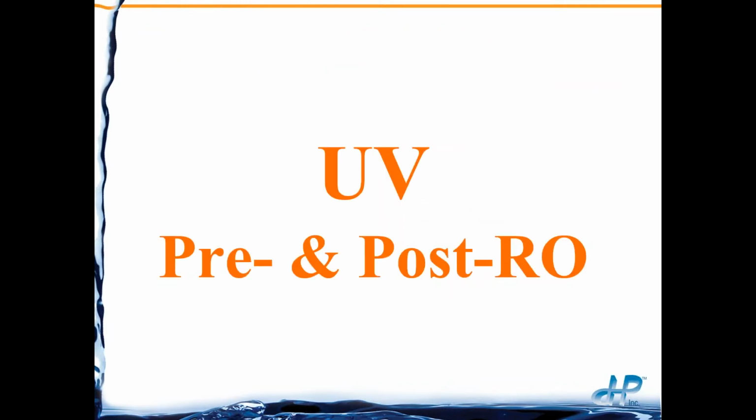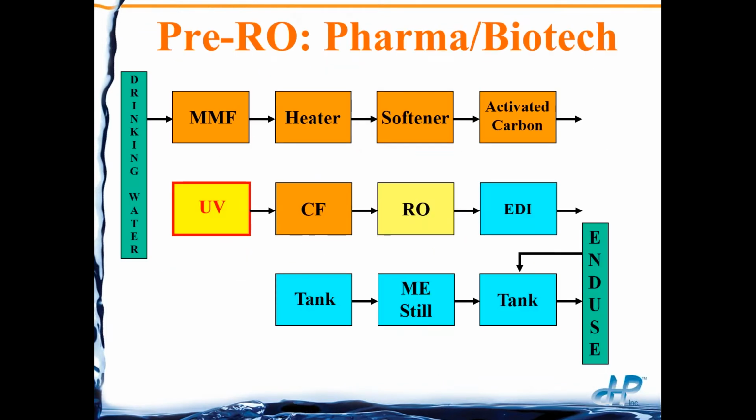So just to wrap up, pre-RO, I don't find it to be common in many industries except for pharmaceutical and biotech in the companies that we deal with. So in biotech, pharmaceutical, it's not uncommon to see UV in front of an RO unit for bacterial inactivation and/or dechlorination.